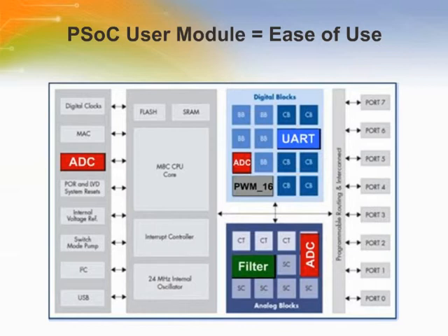The microcontroller and the digital and analog blocks are routed to I/O using programmable interconnects, providing even more flexibility. This flexibility in I/O connections is particularly useful in capacitive sensing applications, where reduction in parasitic capacitance and optimization of signals is so valuable.